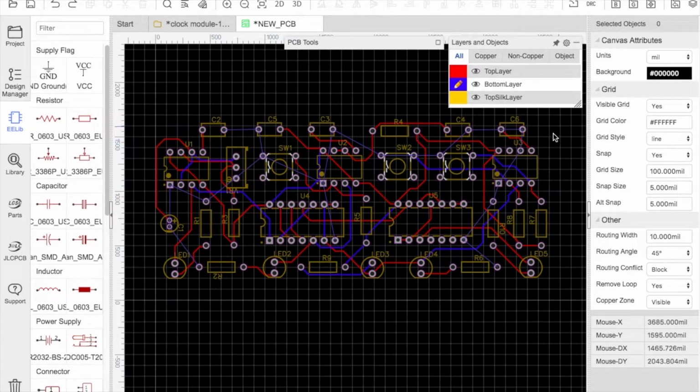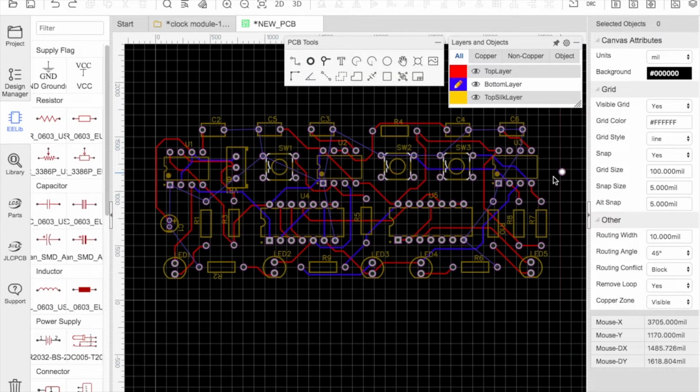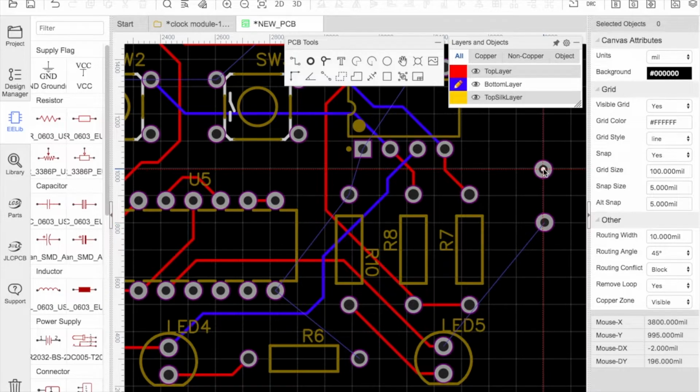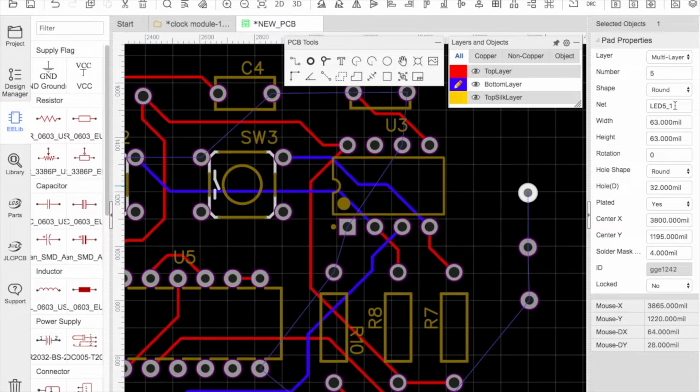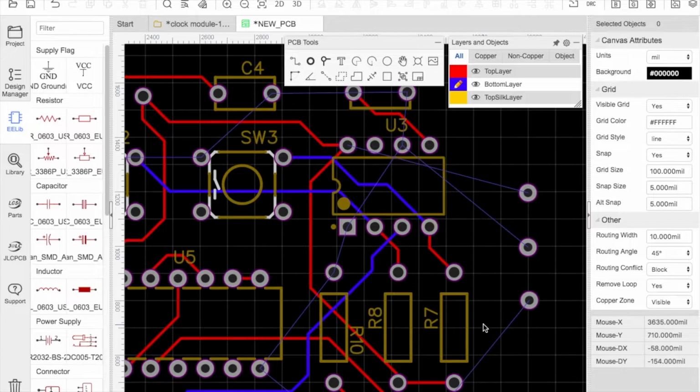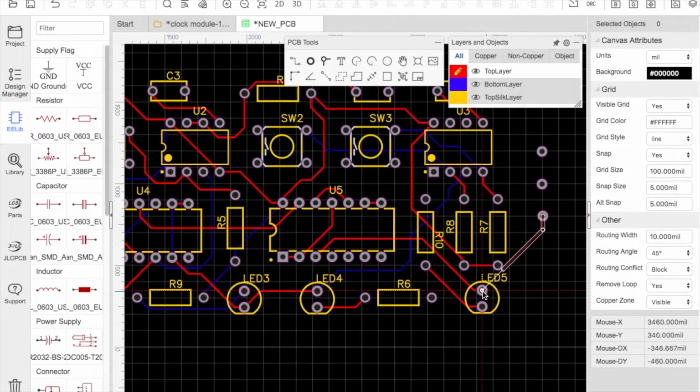So now I need to put two pads in the PCB where I can connect power and ground and connect an output. And so now I'll change their nets to what they should be connected to, so this can be power. So I'll do VCC. This can be ground, so I'll do GND. And this can be the output, so now I can connect this.